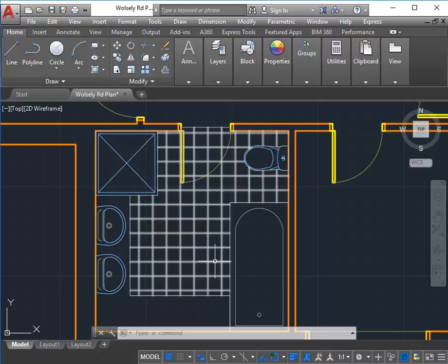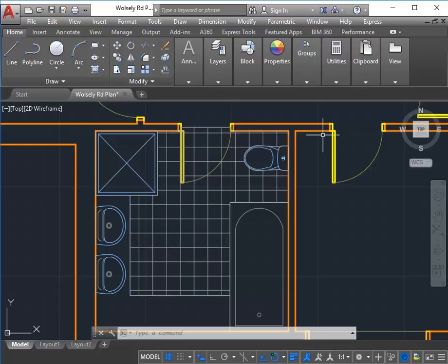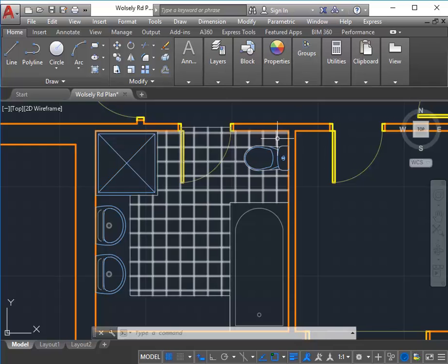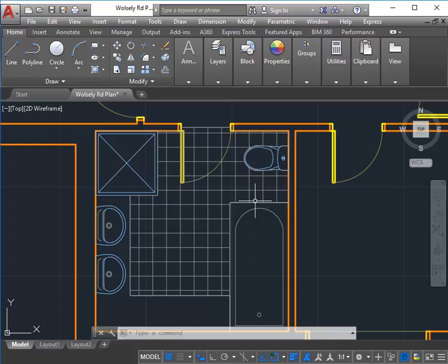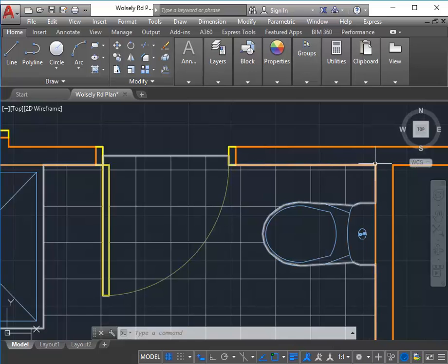So, yeah, where you've got the longest area, that's in line with something that matters, and in this case, maybe the wall in the corner there, even though there's not much of a wall surface there, it would extend onto the bath, so maybe you could set out from this corner here. Okay, so that corner there, I'll say is my set out point.